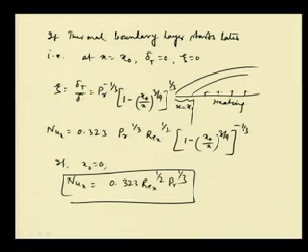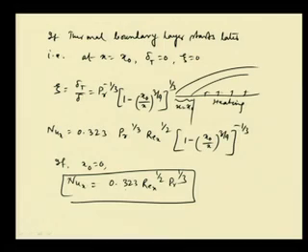Now, all these expressions, and particularly these coefficients, these numerical values we have found, depend on the kind of velocity profile and temperature profile we are using. As we have seen previously also, the third order polynomial velocity profile performs well and is comparable with the exact analysis.